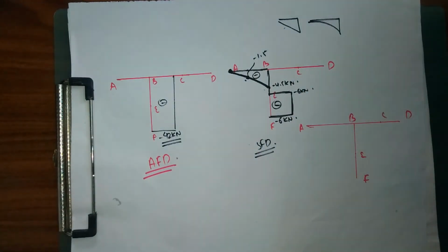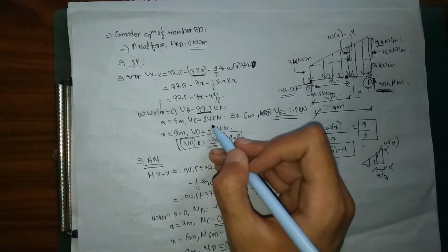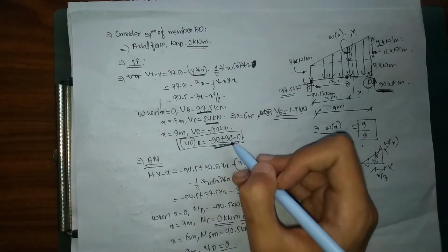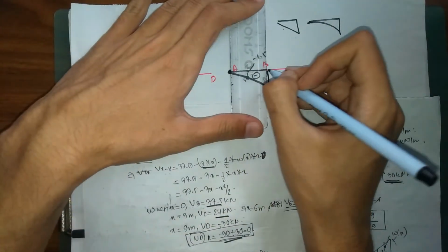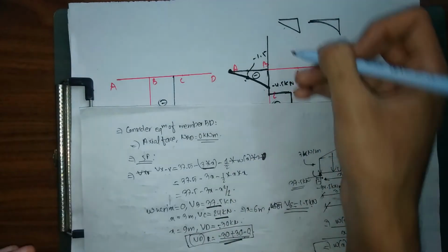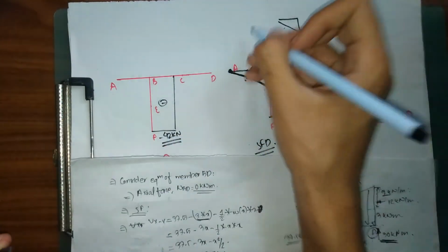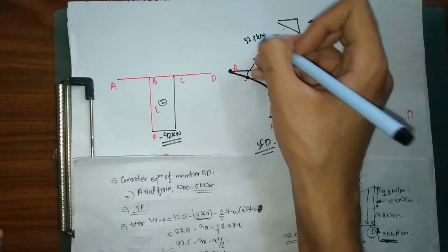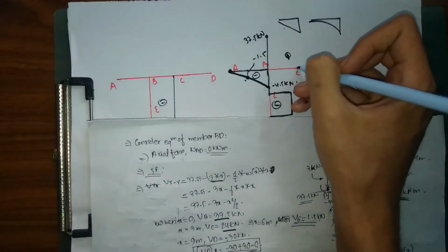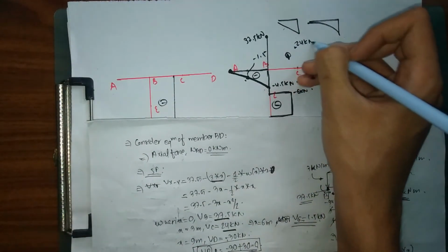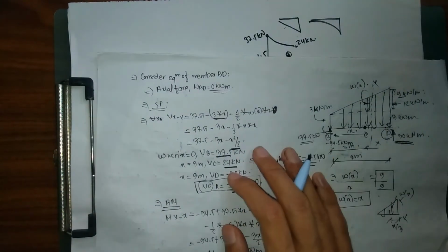Now the shear force diagram for my member BD. I have got my shear force as 37.5, 24, minus 30, 0. So at B it is 37.5. So let me draw a straight line, positive. I'm going to draw my positive upward. I have drawn my negative downward and positive upward, same as for my axial force as well, 37.5 kilonewton. And next at C I got 24. Again parabolic, because as you can see here, I have x square in our formula. So draw it parabolically.